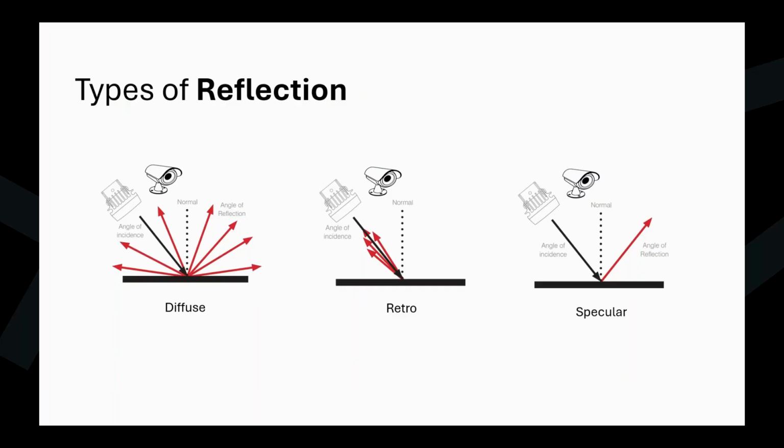And of course, this has to be taken into account when you're thinking about the camera placement. So if, for example, you're looking at European plates, which are commonly retroreflective, apart from Belgium as mentioned, then you want the camera to be very close to the lighting source in order to make sure that the lighting is all bouncing back into your camera.